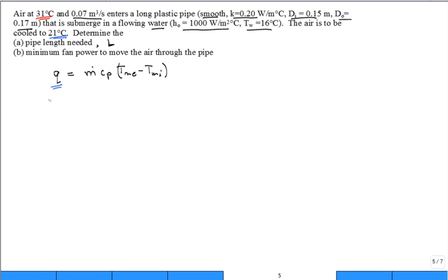So the rate of heat addition, Q, is equal to h times the area. The area here is pi d L times an appropriate driving temperature that drives the flow. So wouldn't that be our delta T log mean? Sure, that would be our log mean temperature difference.